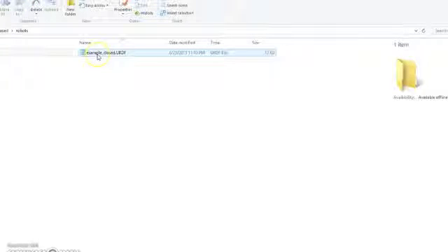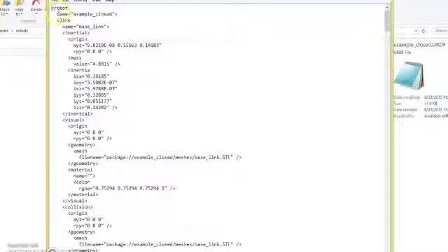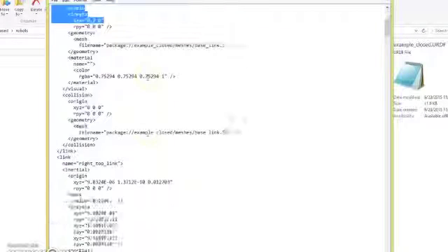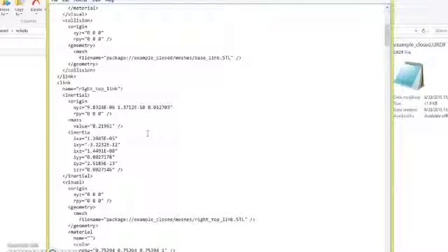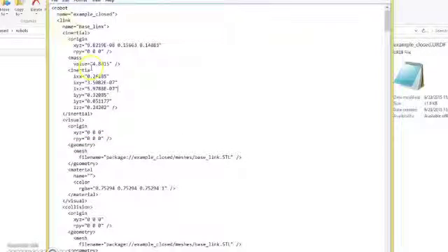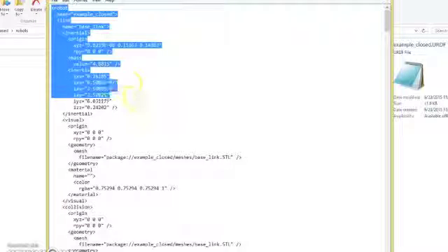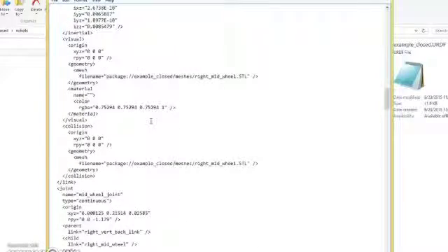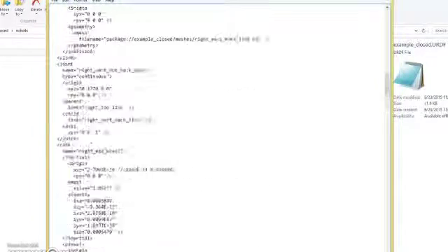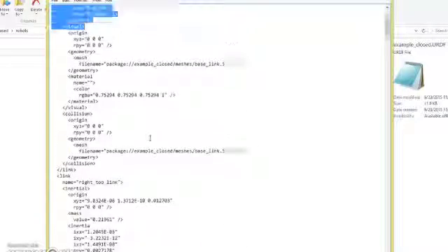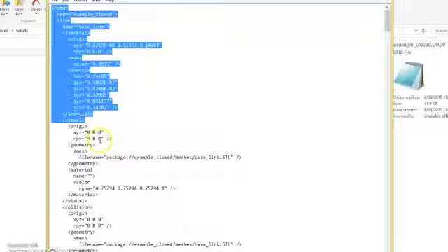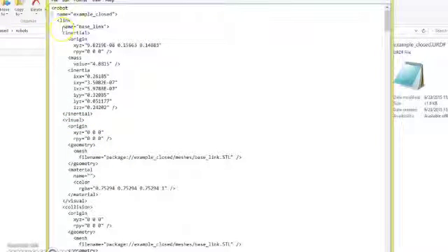The robots folder contains the exported URDF. Now this is interesting to look at because you can check again to make sure everything was created correctly, and also we can look at how one might create a URDF without using the exporter. As you can see, it can become a significantly tedious process, which is why I personally like the exporter. But if you were to create a URDF or SDF on your own, you would use this structure. This is the URDF structure. If you had the SDF structure, you create the SDF structure, and you'd input these values as shown.